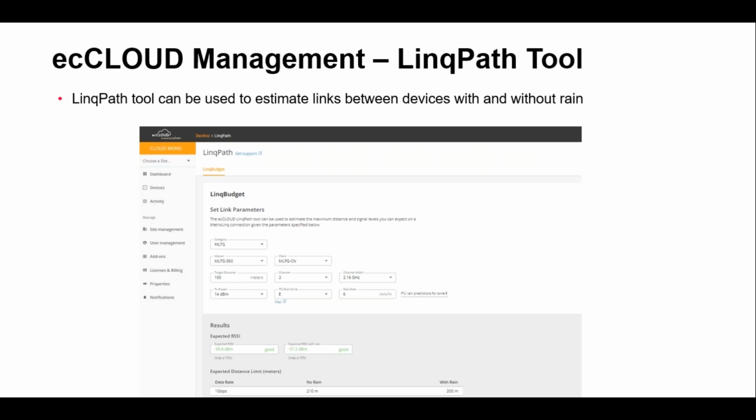That's the worst case scenario. Pointing out the Terragraph product, if you notice, I haven't talked about 5 gigahertz failover. The MetroLink has a 5 gigahertz failover, so maybe you can get away with a further distance and let it fail over once in a while. With this Terragraph, you have to design it with enough signal margin in mind, because you don't have the failover to 5. So you have to shrink everything in a little bit, but the EIRPs are much higher now with the Terragraph, so the link budgets are much bigger.